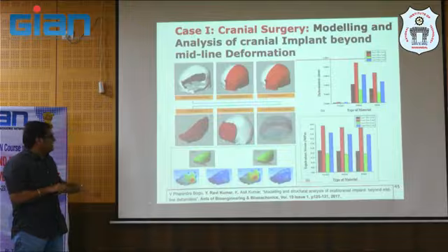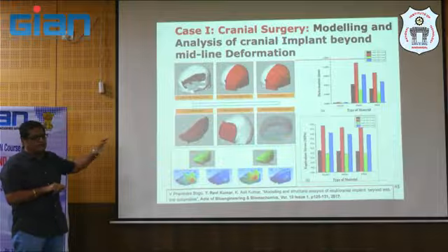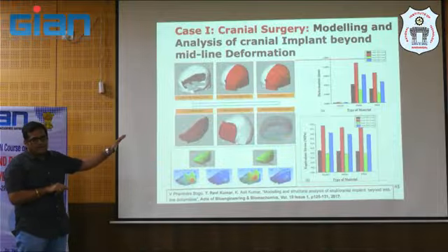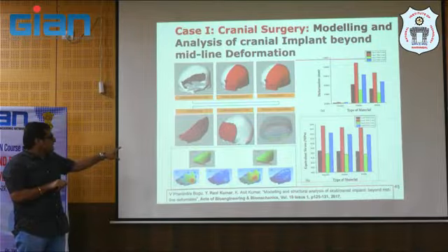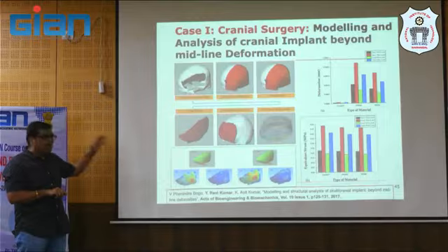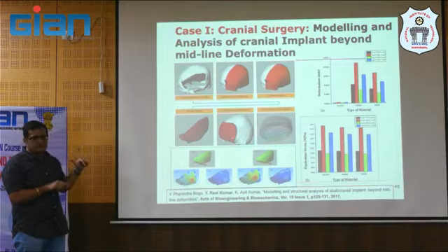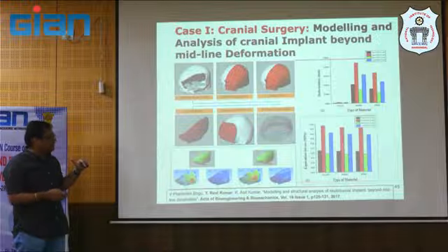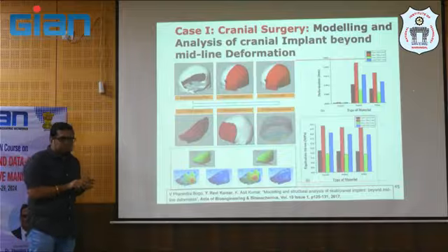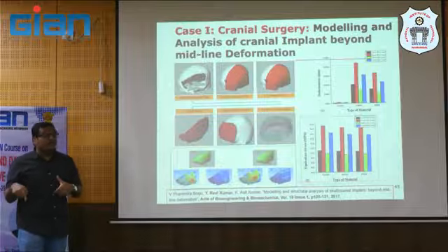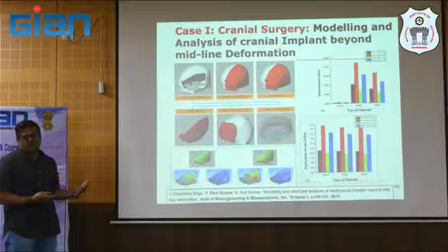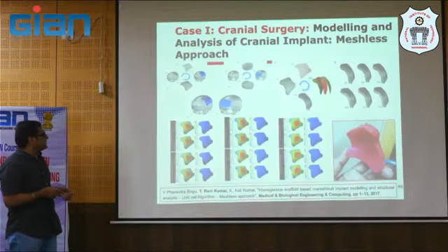Sometimes we need to simulate the number of fixation points. You are going to fix this implant against the skull of the patient, and depending on the location of those fixation points, the pressure of that cerebrospinal fluid will be varying. So what could be the optimal fixation position of these screws, and how many screws, right? So we can very well simulate such a thing, and the material property also. You must have a material which is biocompatible, and your facility must support such a material, right? That is another criterion which we need to understand.